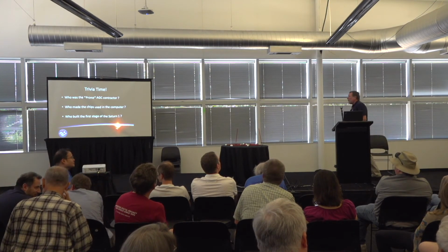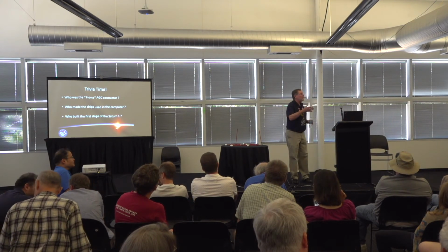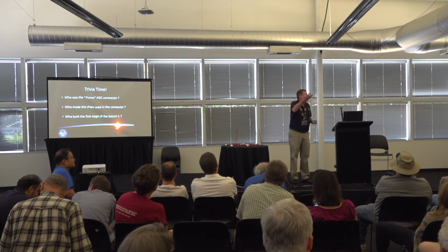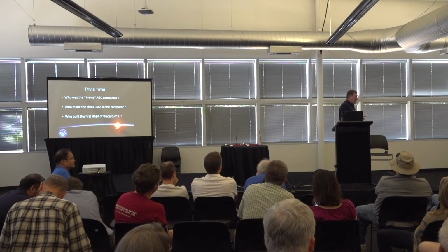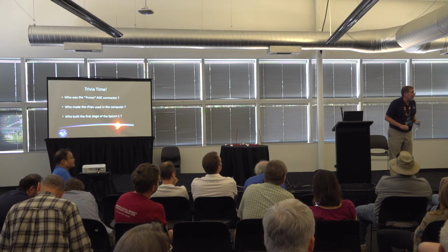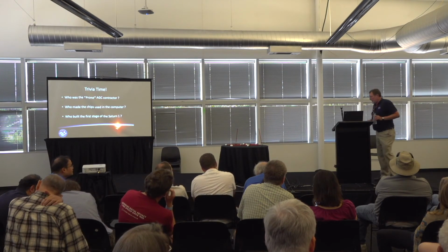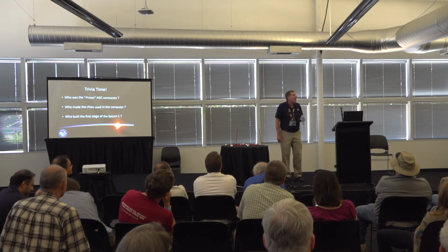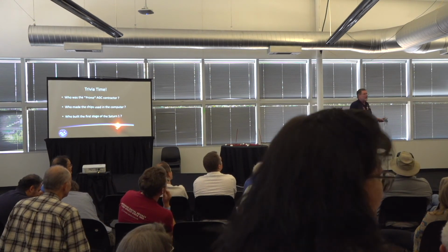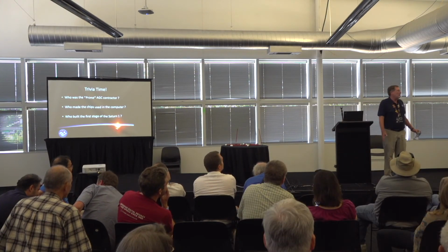What is program 65? Okay. The descent to the moon was a number of programs, separate ones for separate phases. P-63, initial braking. P-64, approach. P-65 was completely automated landing. P-66 was pilot input to the landing. If they had used P-65 on Apollo 11, they would have landed in the middle of a field of boulders at the bottom of a crater.